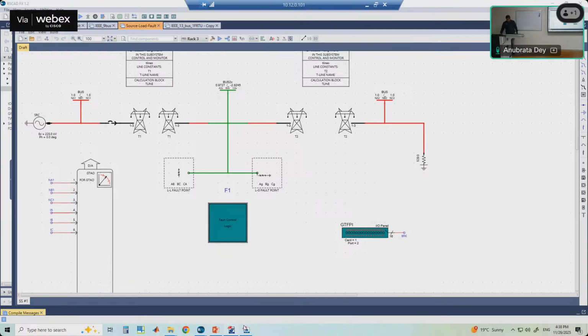So now we will see this GOOSE communication. This is a similar setup. Now we will see that HIL that we have talked about previously. From RTDS, we are giving it from the GTO card to the amplifier, and from the amplifier we were giving it to the PMU. Now instead of the PMU, we are giving it to the relay, and then the relay, based on its logic, generates the trip signal, and that trip signal we are giving back here using this GT-DI card.